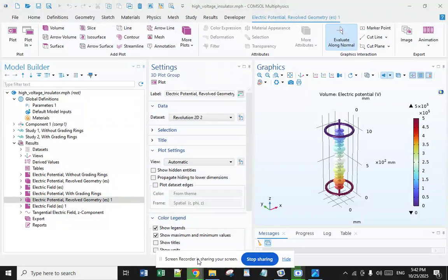And what about the glass insulators? Glass insulators are one of the most common types of low voltage insulators. These consist of a glass tube attached to a metal or porcelain base. The advantage of glass insulators is their high dielectric strength and durability. They are also resistant to corrosion and the effect of sun and wind.